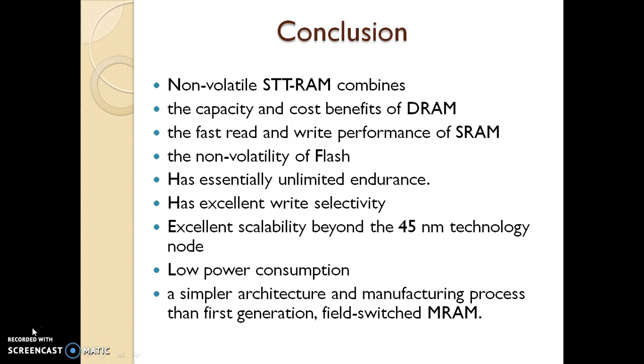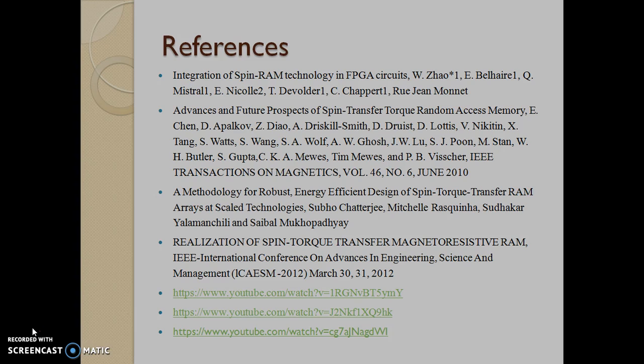Everspin has developed a 64 megabit STT-RAM DDR3. It combines the speed and endurance of DRAM with the persistence of NAND, creating an almost perfect storage medium. Unfortunately, the technology is currently in the beginning stages of adoption. Thus, cost and capacity are inhibiting mass deployment. STT-RAM is proven and is effective, and it eliminates the need for power fail capacitors. STT-RAM has immense potential for future development.